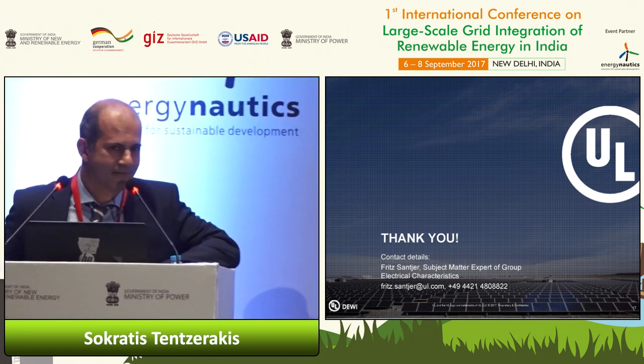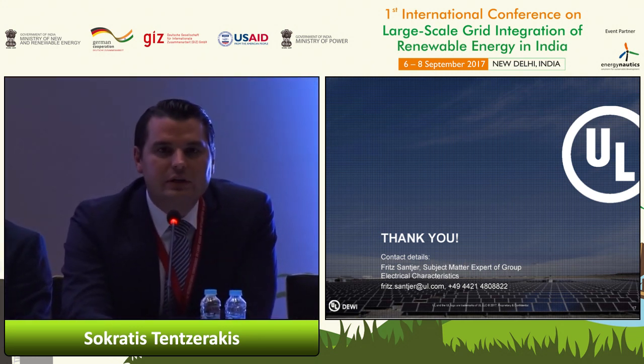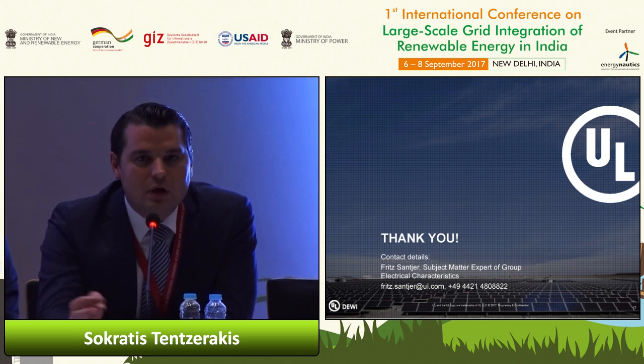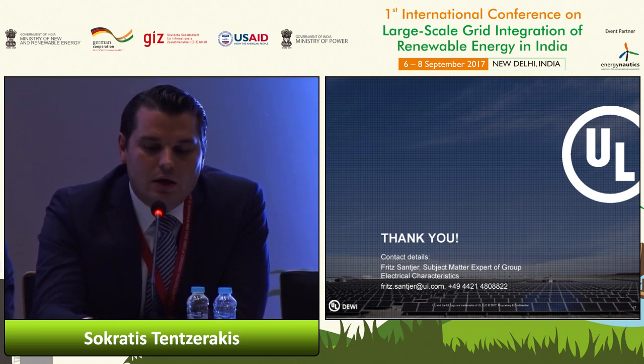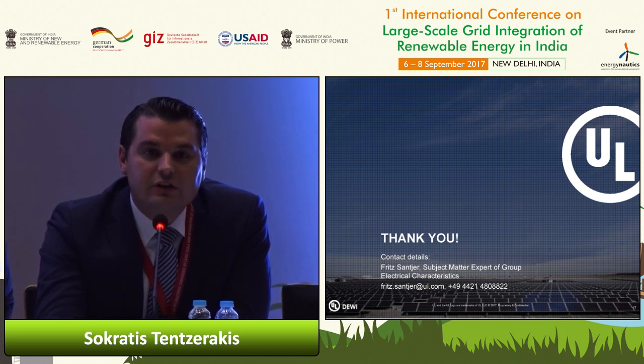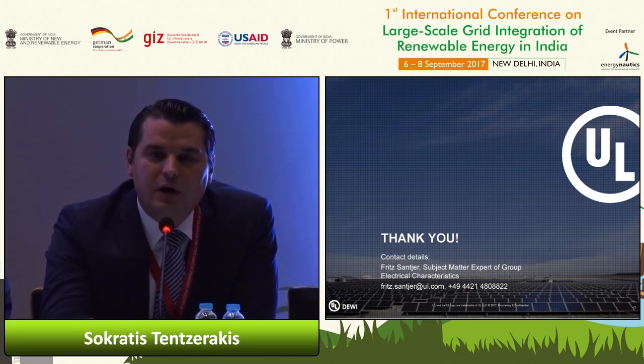An aging effect you don't see, at least for LVRT or HVRT capability. What you definitely see is, for example, when there was an outage or an incident that happened. For example, there was maybe a tripping of a wind farm. It may happen that after such a tripping, the parameters at the wind turbine or even at the farm controller are reset to default mode, and are not parameterized according to the commissioning.